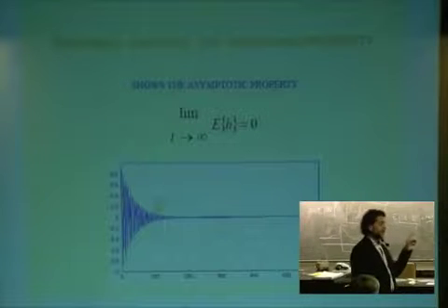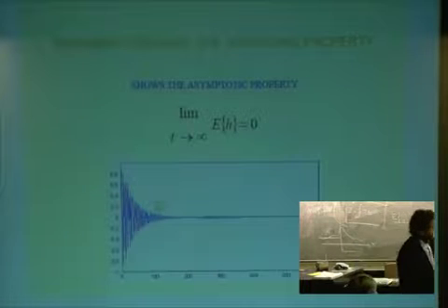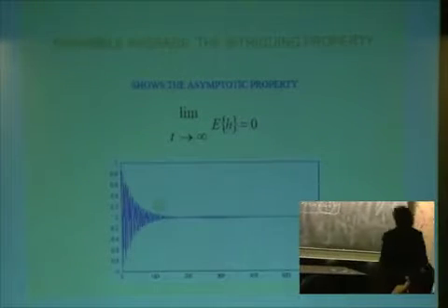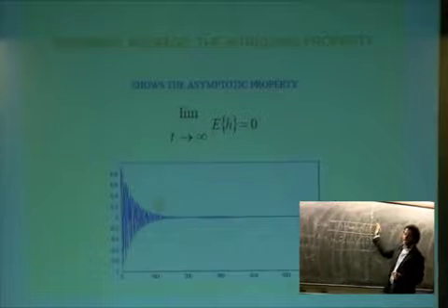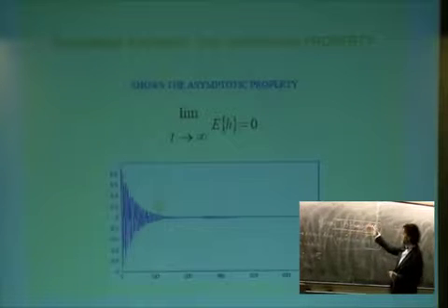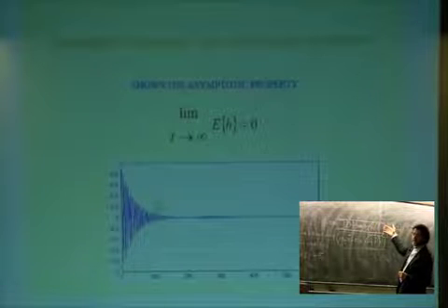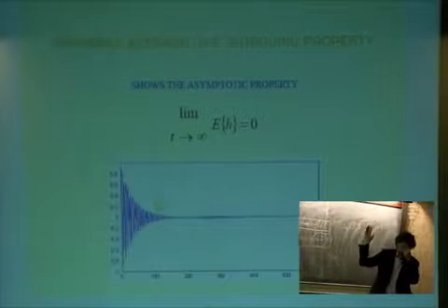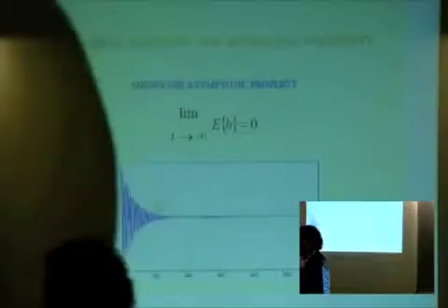This is a very interesting property because it means that the system we are investigating, even if it is finite, suppose that you have a system like this, but it's finite. If you take a population of random systems like this, in which you have a distribution of the natural frequencies of this pipe, and then you take the impulse response of this pipe and the average, well, the average has this property, so it tends to vanish.